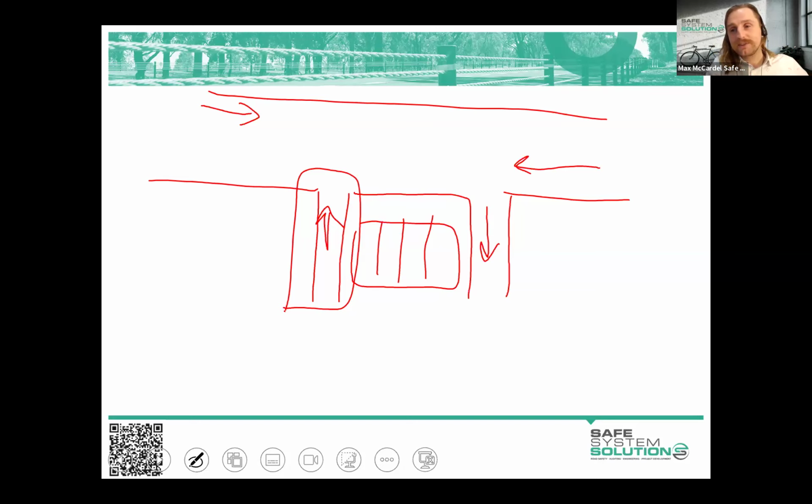I think it's pretty reasonable to say that there will be reductions in traffic volumes, so exposure would be influenced. Very important, though, to acknowledge: where is that traffic going? Because if they're using an adjacent corridor, that's where they're getting pushed to use instead, to complete their journey to get wherever they want to get. What are the implications of that? Because potentially this corridor where you're pushing them to is also not suited.